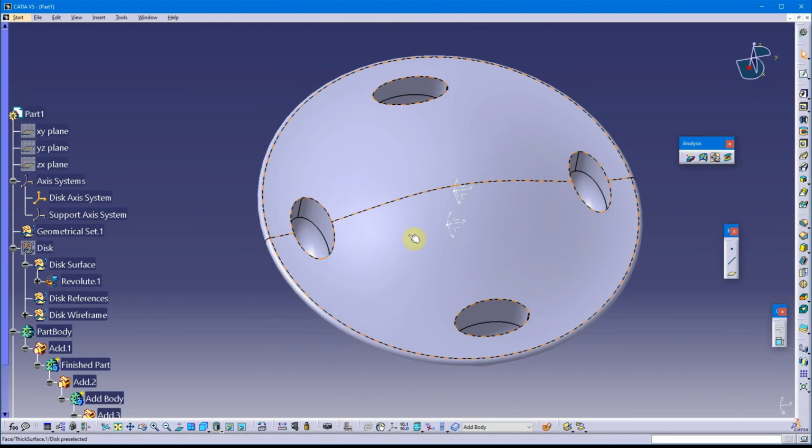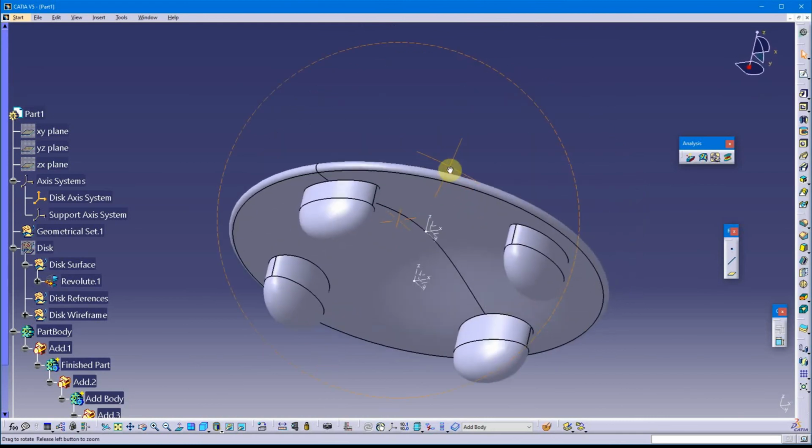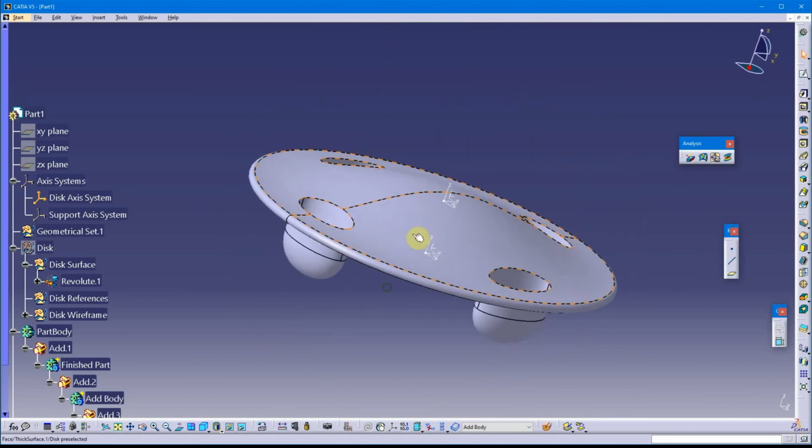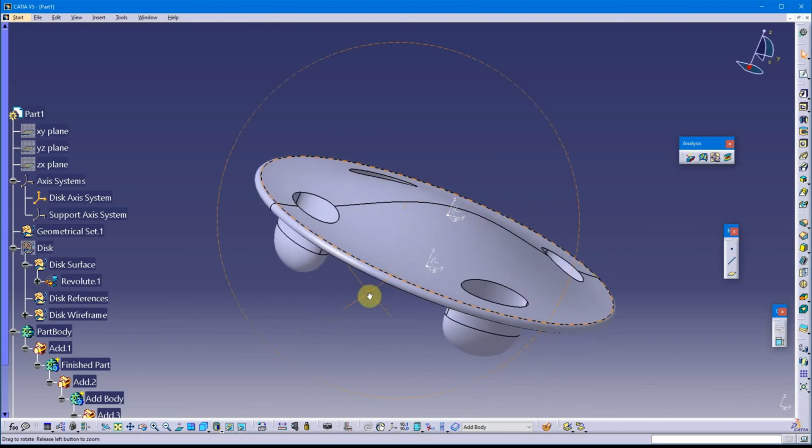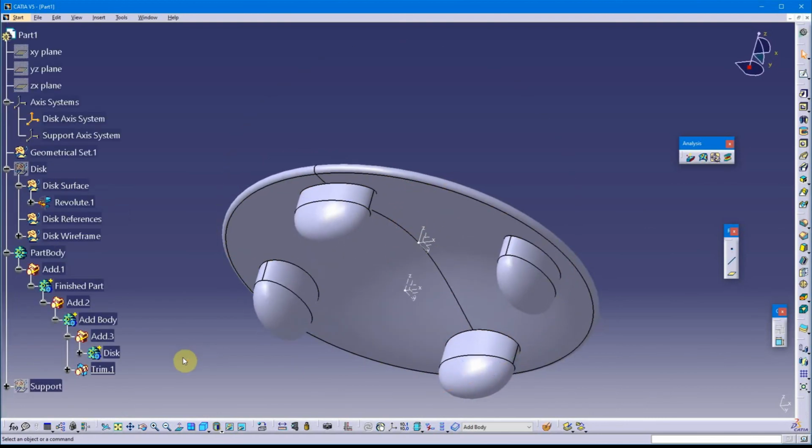And if you were thinking about doing an edge fillet here, I could pick about any face here or here. It's going to propagate over these tangent edges and hit all of the G0 edges. I'm going to give that a shot.